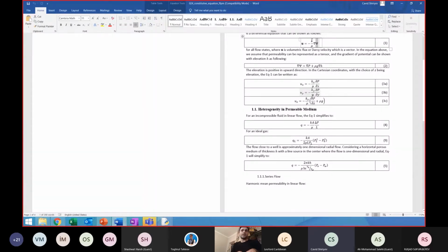Okay, and in this session, we are only talking about Newtonian fluids. And Newtonian fluids obey this constitutive equation that is shown here. Okay. In general, we can have the Darcy equation for non-Newtonian fluids as well, but it's out of scope for now. Numerical solvers can handle those scenarios as well. Although the problem becomes nonlinear, and it's not robust all the time, it can still be handled for non-Newtonian fluids. But for now, we are only focusing on Newtonian fluids, and this Darcy equation is the constitutive equation that we are going to use for our problem.